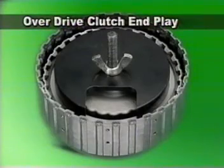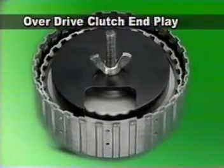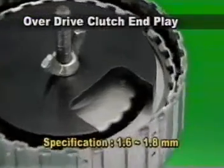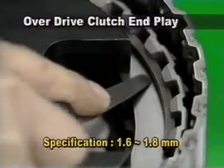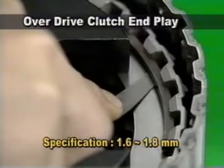Overdrive clutch can be measured the same way too. If the measured value exceeds the specifications, replace the snap ring with one of the 15 different thickness snap rings, the same way as with the underdrive clutch.